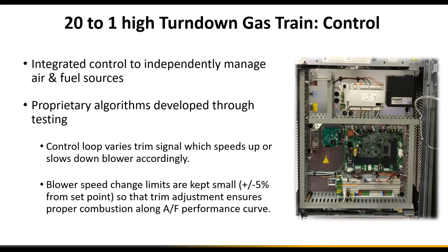we're basically sensing fuel and air, and along the entire heating curve, along the entire calibration curve, we have 9 points where at the factory level, the fuel valve and the air damper are adjusted and fine-tuned, and then anywhere between those points, they automatically adjust themselves in harmony.